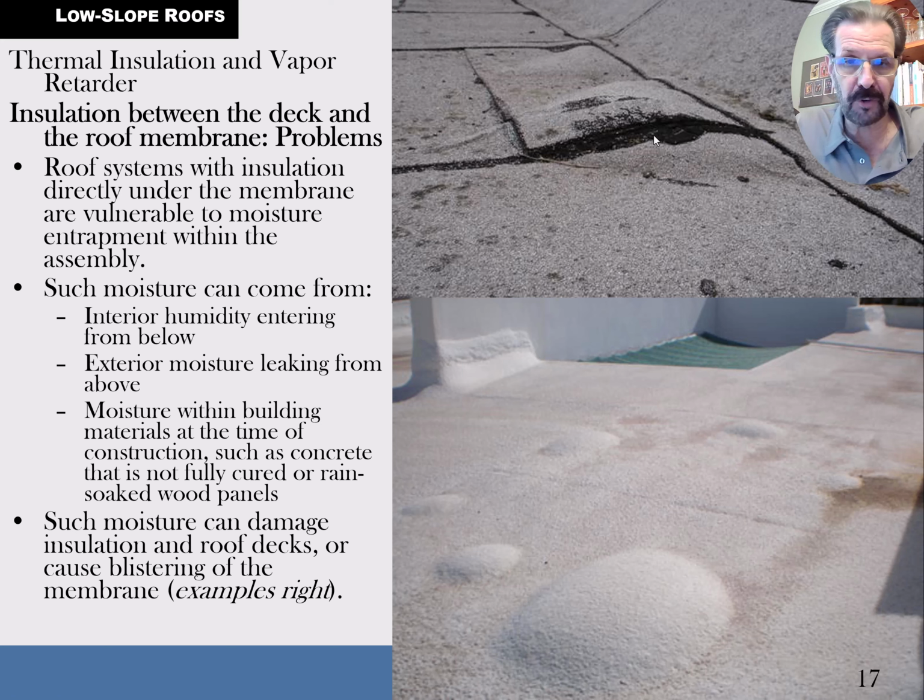And you walk on those things and you can break up that roofing. So next thing you know, just having gone up to inspect a roof, look around, you step on some of those things and collapse them a little bit, you've created roof leaks. And next thing you know, you break it, you bought it. So be very careful when you go to inspect a roof or look up on an old roof for whatever reason, where you walk. You also should not walk anywhere near these edges because the roofing is generally not glued